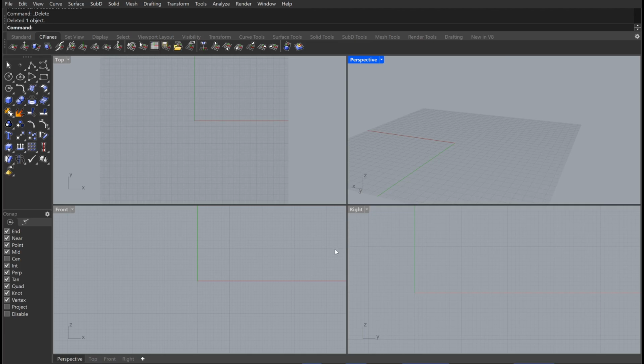If I wanted to make my 2D shape in the vertical, in the X and Z axis instead of the X and Y axis only, then I have 2 different methods of doing that. First, I can come to the shapes over here, cascade the tab, and select this icon with green and red lines going through it. If I select this and come to our plane over here, now you can see it's making our rectangle. Let's define this as 15 feet, enter, and let's make this 100 feet tall, and press enter over here. So now we have a vertical shape, as you can see.